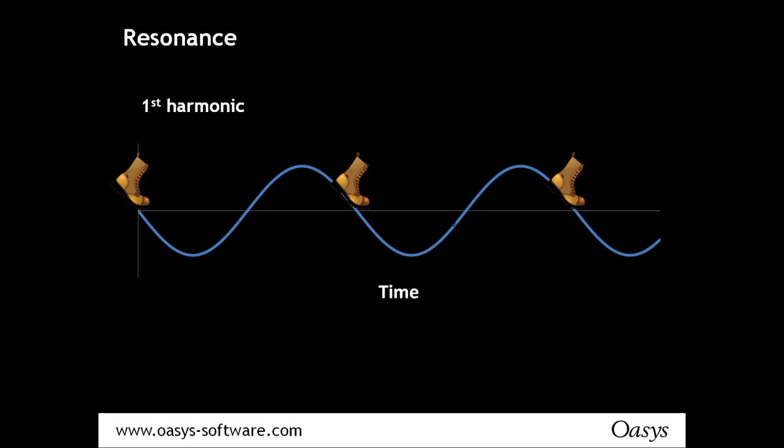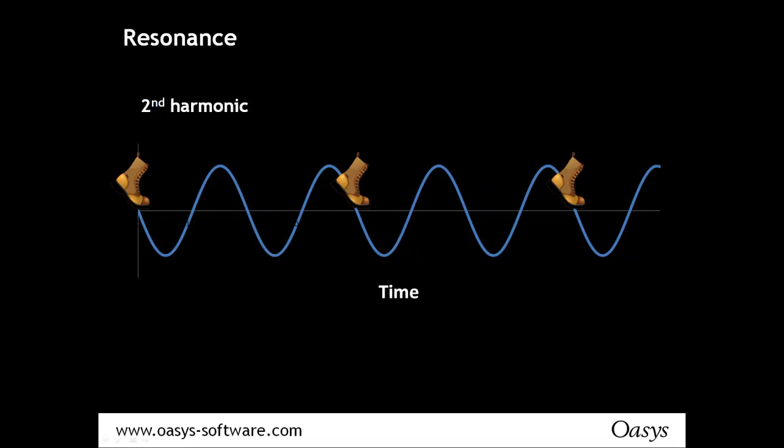Now note this is the first harmonic, so this is the footfalls landing at the same frequency as the floor. Generally for buildings, the design guys say that the first frequency should be about 3 Hertz or more, and people walk typically up to about 2.5 Hertz, which means you don't get the first harmonic vibrations on buildings. Though you do on bridges, because bridges can be vibrating down to 1 Hertz or maybe even less. So you can resonate with the first harmonic.